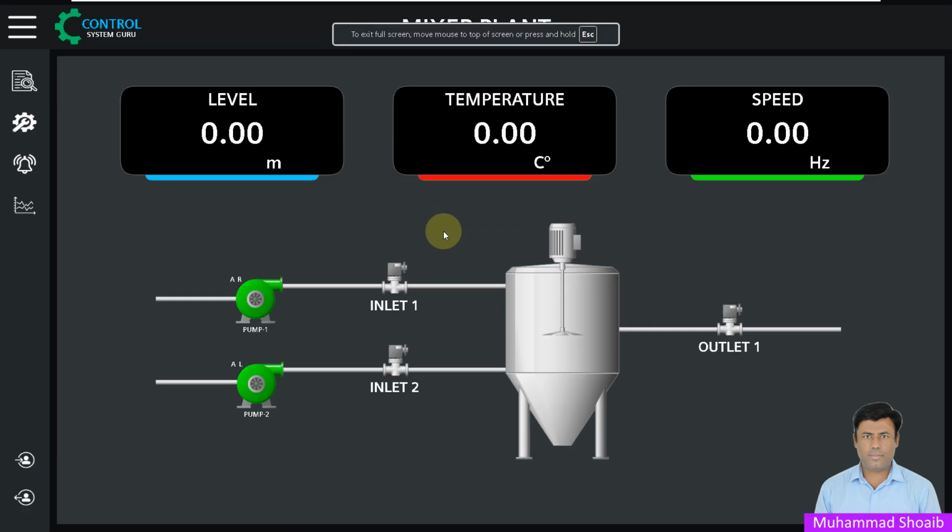So Alhamdulillah, we learned in this video tutorial how we can configure the UDT in WinCC Unified, and we also learned how we create a faceplate template object using the UDT. Then we created the instance from our objects, and we learned how we can reuse the UDT for our multiple similar objects, pumps or valves. In the same manner you can use this UDT for pumps, valves, transmitters.